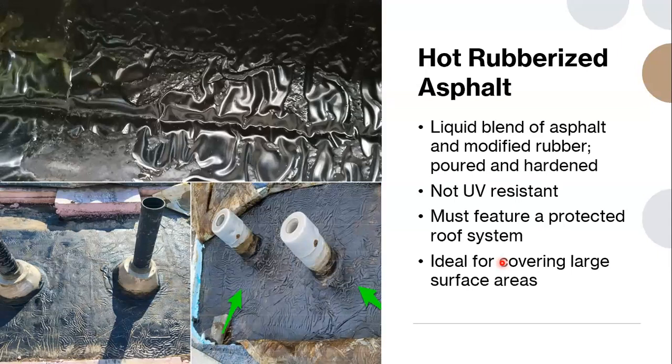Similar to a lot of other roof systems, you want to make sure that all of the penetrations are sealed, the flashings are secure, dealing with any rusting from any of the flashings, and ensuring that your drains are clear. And then on top of that, we would always say that there's usually a few puncture holes throughout the roof. So doing some spot repairs each year and maybe the reinforcement of some of the seams. But with TPO roofs, it is really important to do more regular inspections because of the membrane concerns of punctures.